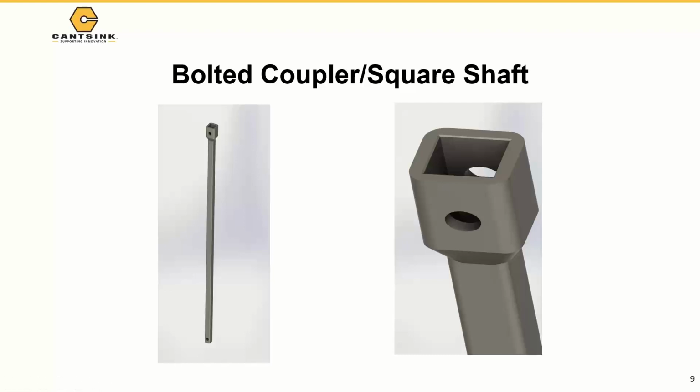Of course, when we design helical piles, we make sure we design for the mechanical capacity. We check the mechanical capacity of the helical pile. That means we check the tension and compression of the shaft, and the bolt bearing. We also check the torque, how much torque that shaft will take. These are what we call the mechanical capacity of the pile.